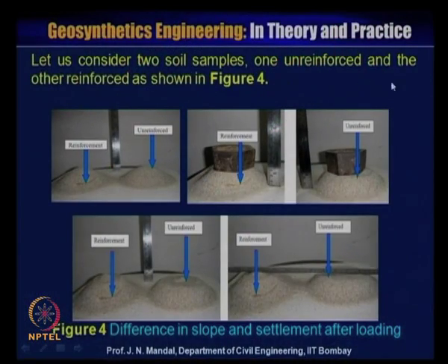Now let us consider these two soil samples, one unreinforced and the other reinforced. This side is the unreinforced sample and this side is the reinforced sample. You can apply the load in the reinforced case and in the unreinforced case. After applying the load, you can see the difference in the settlement between the unreinforced and the reinforced case, and the pattern of the slope. You can see a much steeper slope in the case of reinforcement.